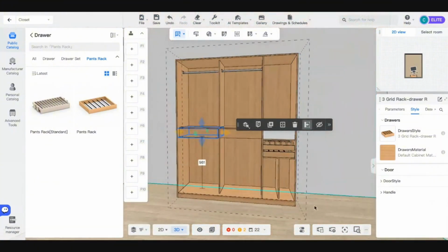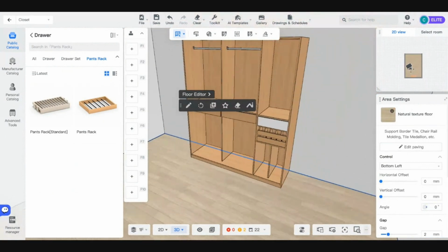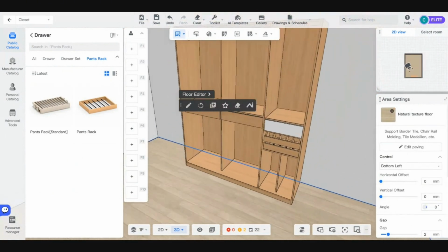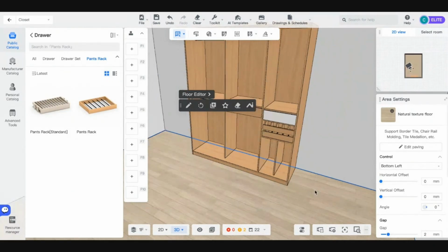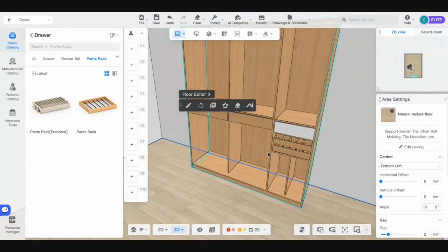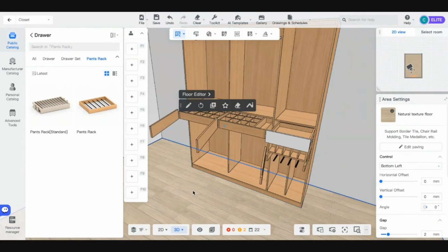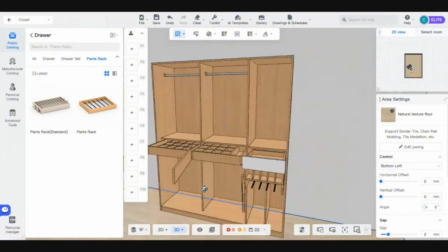Okay. In Coohom, in the kitchens and also custom cabinets and wardrobe, there's also a shortcut, so you can see all the racks or doors open. In this case, you can press Command O, or in Windows it will be Control O. So it will open everything. Okay.